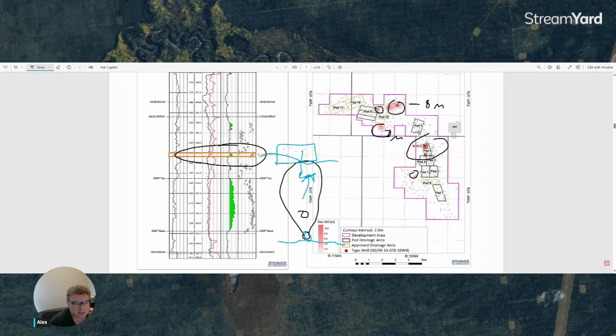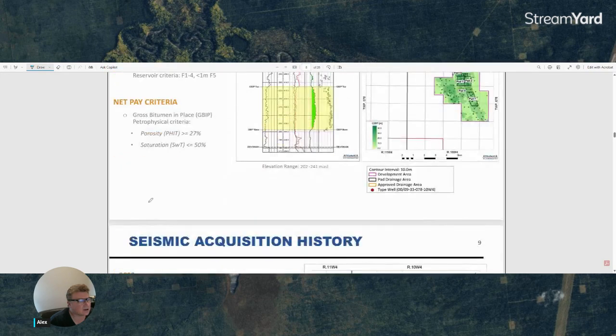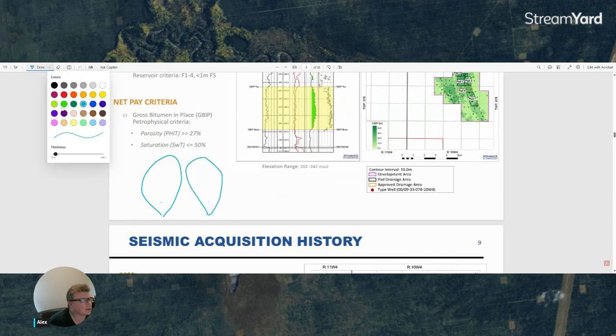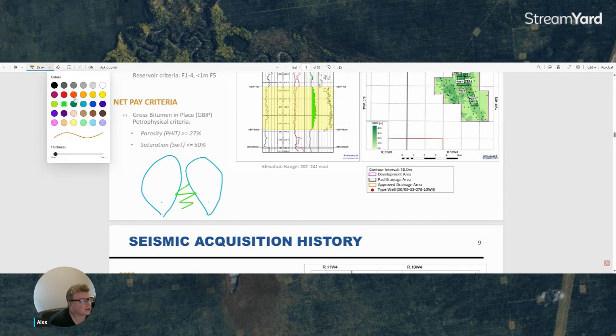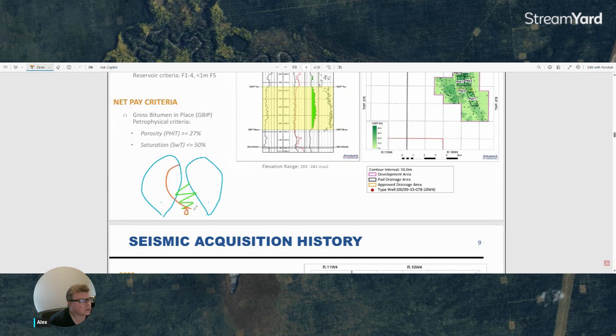Okay, let's address some questions. To improve the continuity between injector and producer. So is that in the context of infill wells? Yeah, exactly. So if you have a steam chamber here and one steam chamber here, and that zone, let's say, is now mobile right here, you'll put an infill well here, and you can drain that region, right?